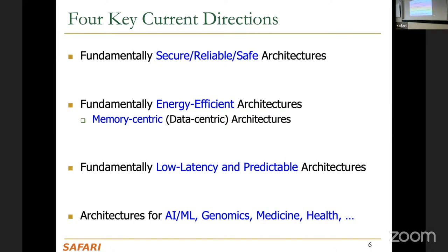Memory is also very parallel, right? Imagine petabytes of memory. If actually all of the cells are doing computation at the same time, that parallelism is much larger than the parallelism you have in the processors today, just because of the sheer amount of memory that we have, right? If you actually look at the transistor counts, I think I've shown this in a DDCA lecture this semester, but in a huge supercomputer, more than 97 or 98% of the transistors are dedicated to memory. I don't believe this number includes storage, but memory, DRAM, for example, because it's much denser, right?